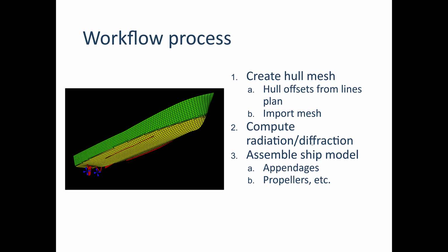And then the diffraction calculation, which is where the ship is still and incident ocean waves are generated, and the interaction effects with the hull from a wide range of frequencies and forward speeds are resolved. So the diffraction is like what happens to the wave as it deflects around the hull and the force that it creates. Finally, there's an assembly of the ship model.